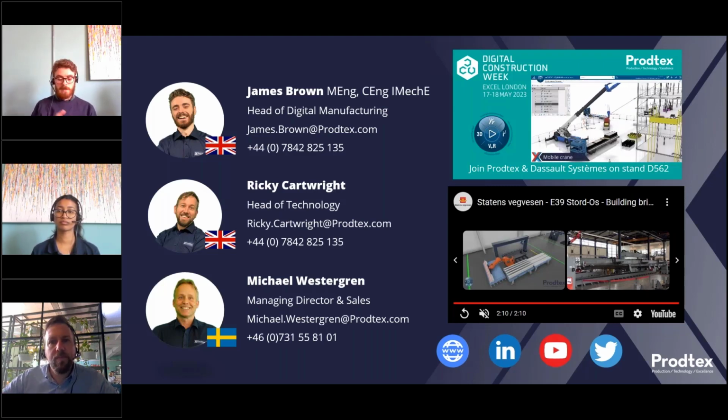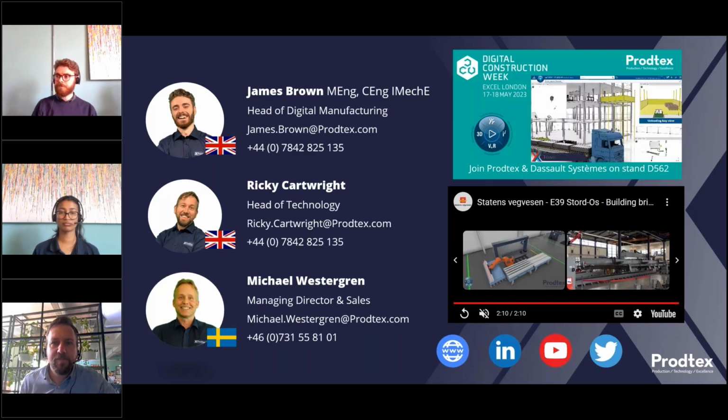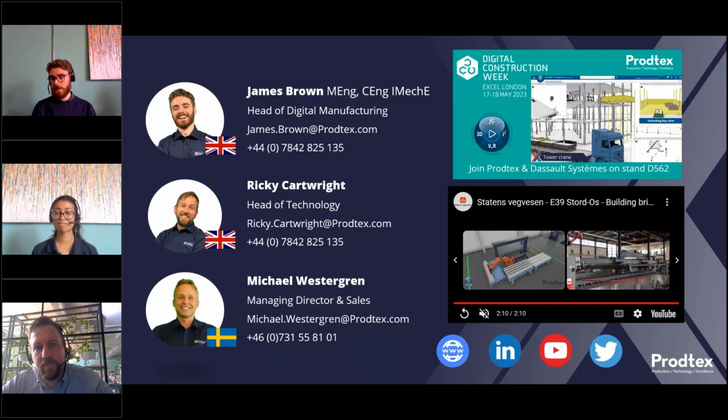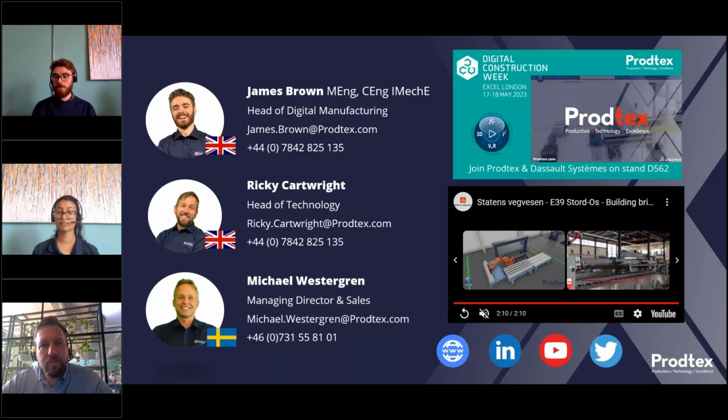Similarly for the equipment, like the telehandler, the mobile crane, the crane, if you have custom equipment as well, maybe for lifting and access, or like the Genies, for those things you normally have preset speeds, preset times, preset equipment mechanics, I guess. In which case, when we simulate that crane, it's giving me the real speeds. It's giving me the real time of how long this thing is going to take, how long the lift is going to take. So again, I'd always emphasize to customers, this is really handy if you want a rough order of magnitude of how long this process is going to take. And it can help you get in the ballpark region early on in the simulation, but that always needs validation.